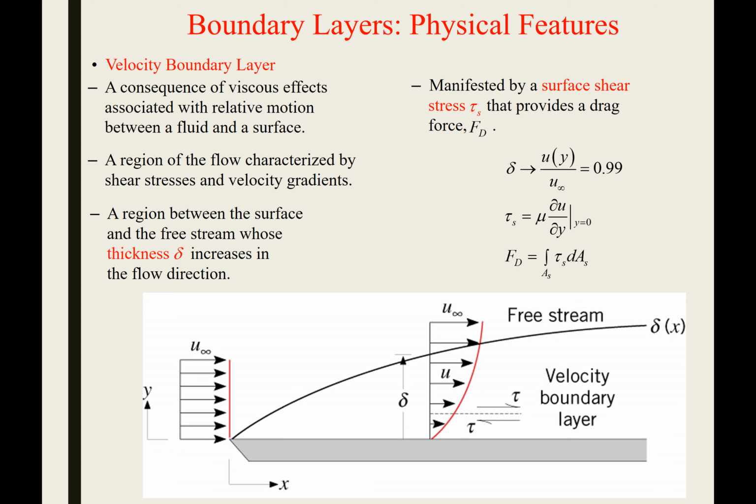In my example, I said that the table was heated, so we have some sort of flux that's heating this table. So that bottom layer is going to start being heated. If you remember, as we've talked about convection up to this point, we've just treated convection as being totally uniform over the whole surface. But what will really happen is the convection will change as that boundary layer grows. That boundary layer will serve as a barrier to heat transfer in some ways. And so as that boundary layer forms, the rate of heat transfer, depending on your x equals 0 or x equals L, could be physically different.